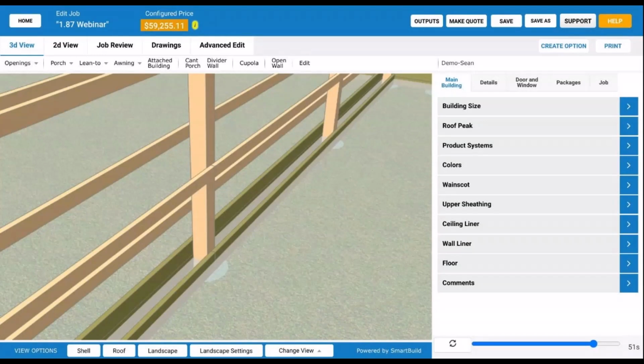Bottom plate. Okay. Is that only for interior posts, or do you do that on the exterior also? We do that on exterior as well. Do you attach anything to it, like the sheathing or anything? No, in a post frame wall it would be the same width as your post. So your skirt board on the outside and inside nails into that, and it makes it a much more solid bottom edge, and it provides a better weather seal. Yeah, we do the same thing. That's the first I've heard of that. That's interesting though.